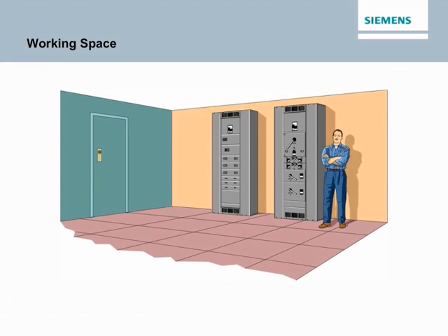Panel board installation requires careful planning to ensure a safe environment for personnel and equipment. Article 110.26 of the NEC covers spaces about electrical equipment such as panel boards. The intent of Article 110.26 is to provide access and enough working space for personnel to examine, adjust, service, and maintain energized equipment. Article 110.26 sets requirements for the depth, width, and height of a working space. In addition, Article 110.26 discusses entrance requirements to the working space as well as requirements for dedicated equipment space for indoor and outdoor applications. If you will be involved in planning a power distribution system, you should familiarize yourself with Article 110.26.